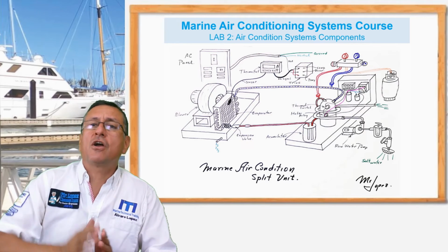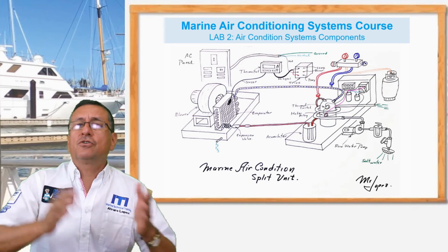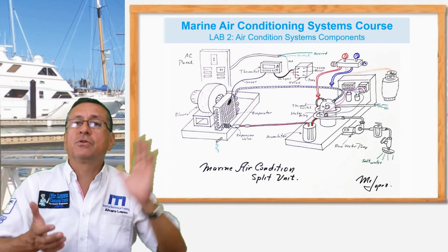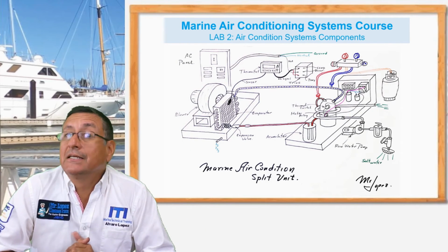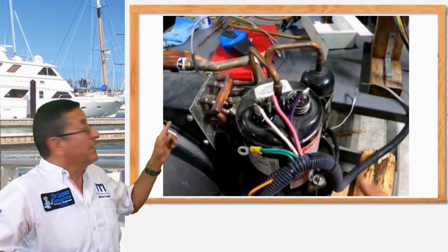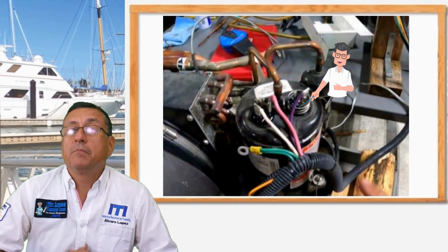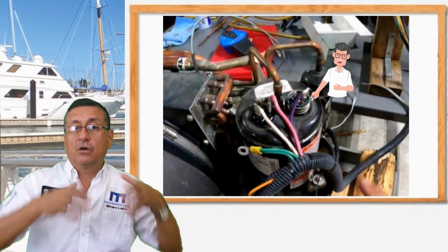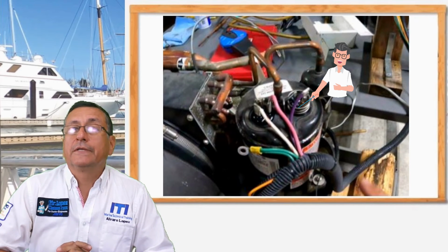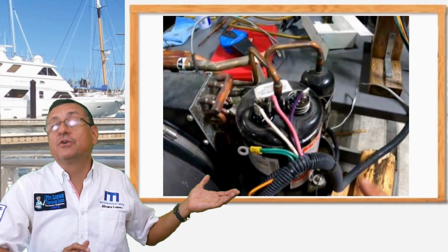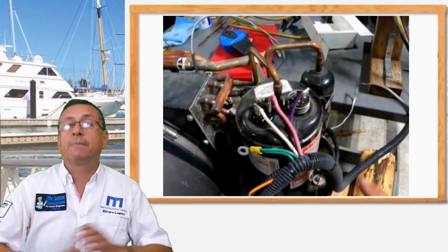Another common fault is my air conditioning system starts, but two minutes later stops suddenly. This is probably, you remember the thermal switch on the case of the compressor? That thermal switch opened suddenly because of overload, high temperature on the case. Or you have a short, the winding of the compressor motor is not good. You need to verify that with the meter.